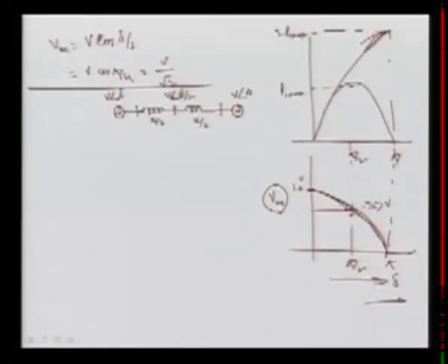Now we want to derive the power. The power flowing here will be equal to the power at any section, so either you can write it for this section or that section, immaterial. Let us write the power for this section, between this voltage and this voltage. So I can write V square upon x by 2, into sine delta by 2, or I can write 2V square upon x sine delta by 2.